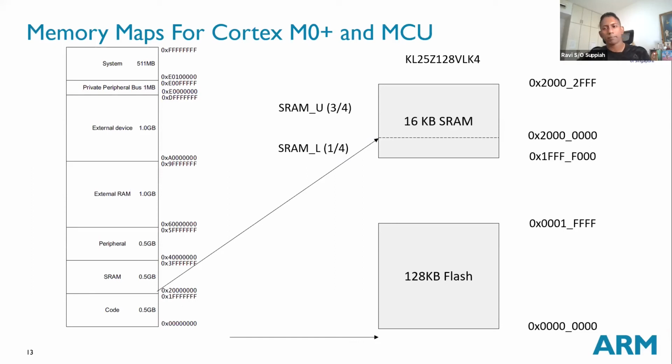Okay, this is the memory map. We will go through it in more detail later on. But the memory map of a system gives us the full snapshot of how the entire memory space is used by the hardware that you have. I think last week when we were talking about 32-bit, some of you were asking about the address range and the data range and so on. This memory map of any processor is tied to how big the address bus is that it has.